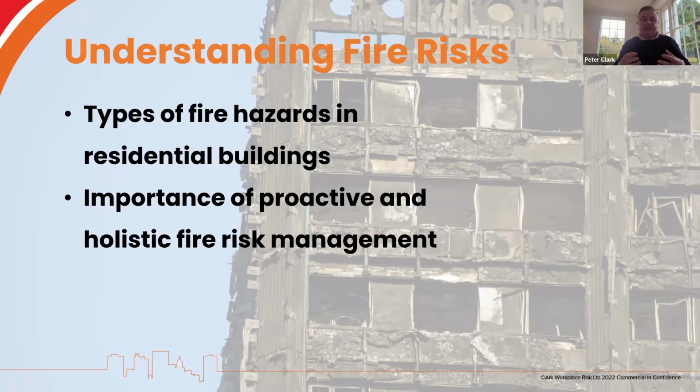And it looks at buildings holistically, and it tells you, look, the most important thing here is that we stop this happening again. How will we do that if we don't cross the threshold and go into the apartments and go into those units? And that's what's commonly known as a Type 3 fire risk assessment. That is a non-intrusive investigation into the common parts and the demised areas and how they work together. So most of the fires, statistically speaking, an incredibly high percentage of fires are starting in the demised areas. So for me, it's foolish to look at just the common parts.